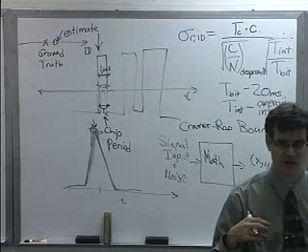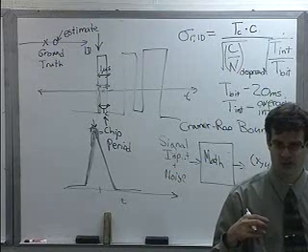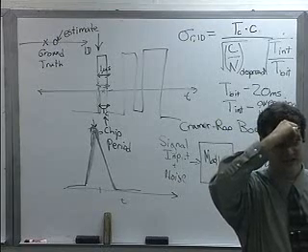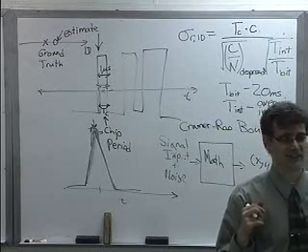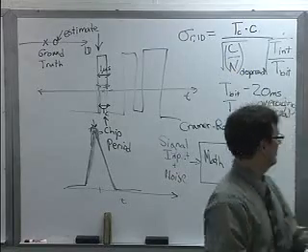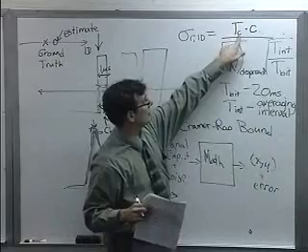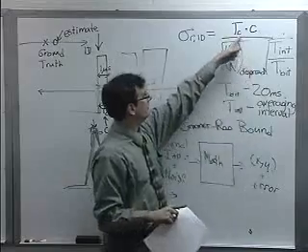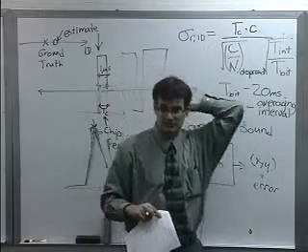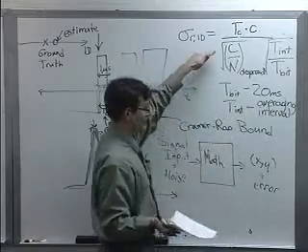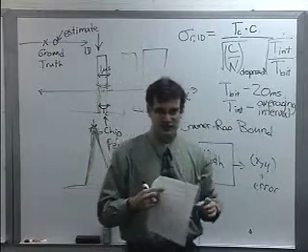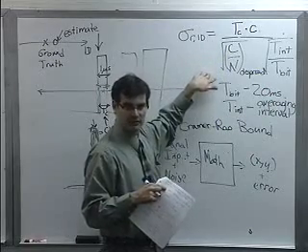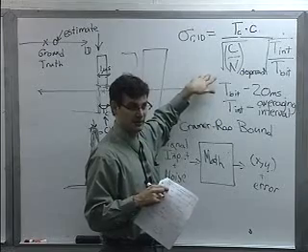3G systems are broadband enough to do that, but especially the early systems like TDMA, I think that had like 40 kilohertz of bandwidth, or GSM, that was like 200 kilohertz of bandwidth. That's actually a lot larger in terms of its bit length, the symbol that you're keying off of. That's a lot larger than this. Coupled to the fact that you don't usually get a very good carrier to noise ratio. If you have a cellular system where you have really high carrier to noise ratio, you are like the world's worst carrier because you're not reusing that expensive spectrum that you had to pay for.